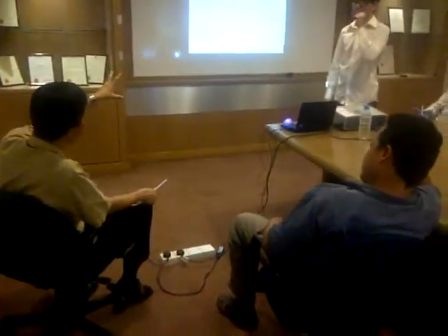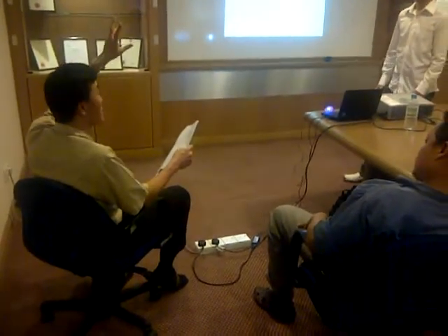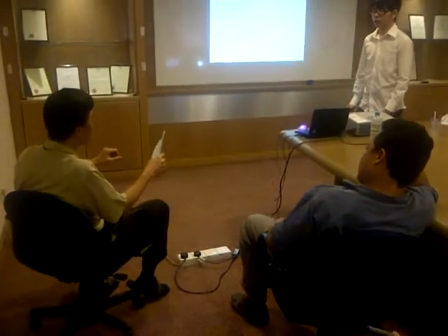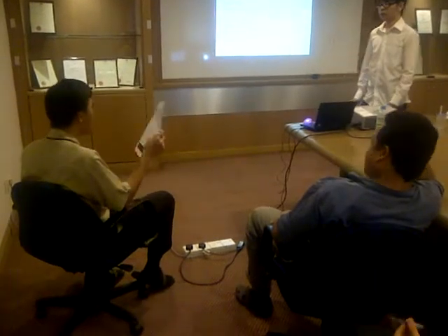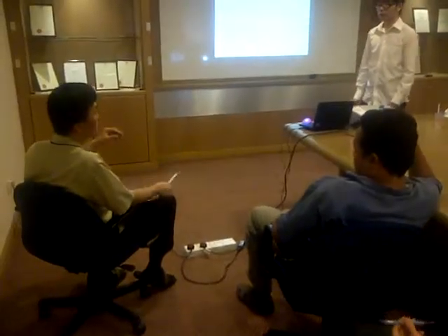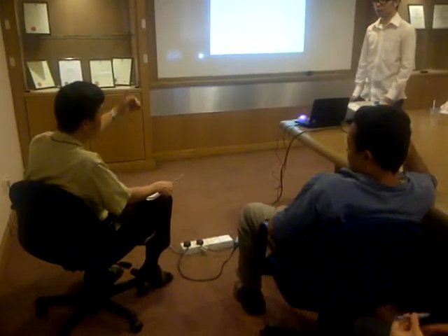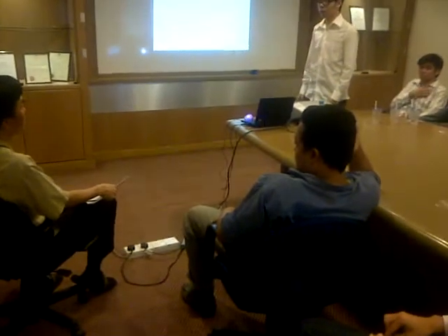But from there, when you design, because switch socket outlet is very subjective, not like lighting. Lighting, when you off, you off. But switch socket outlet, you don't know if people use it or not. Sometimes people can use more, sometimes less. So your diversity factor is very important. If your diversity factor is very high, eventually everything is sized very high. Your DB also very high.